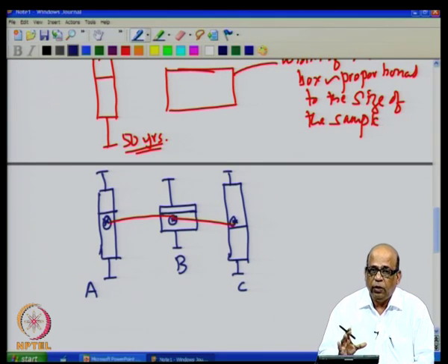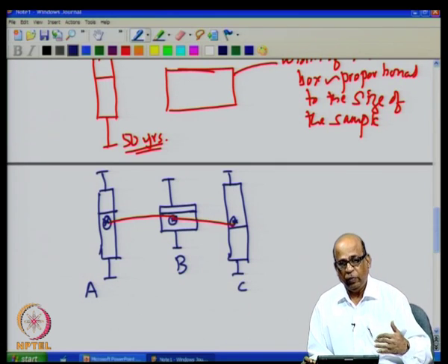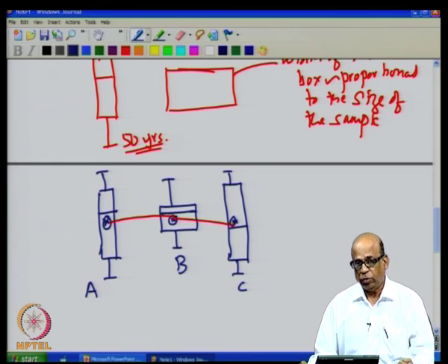The most recent and burning issue in hydrology has been the issue of climate change. I will just give a brief introduction in today's class on what are the issues related with climate change, and then we will see how to address the climate change issues for hydrologic designs using the techniques that we have learnt in this particular course. And specifically, I will deal with what is called a statistical downscaling technique.